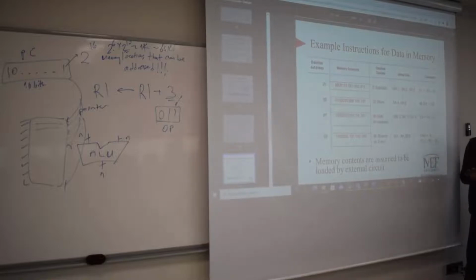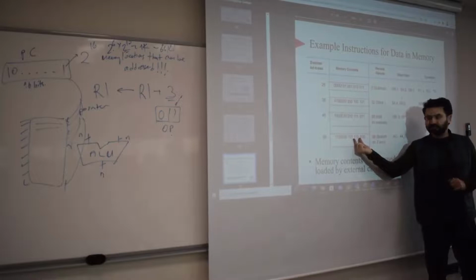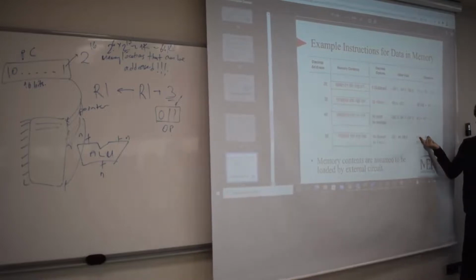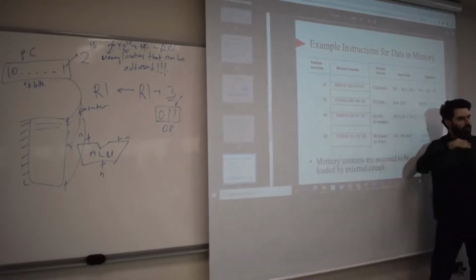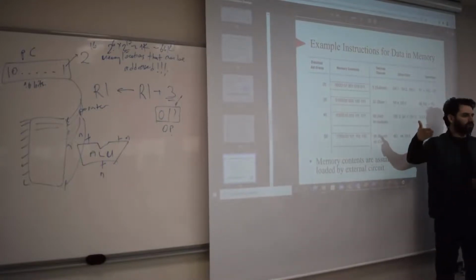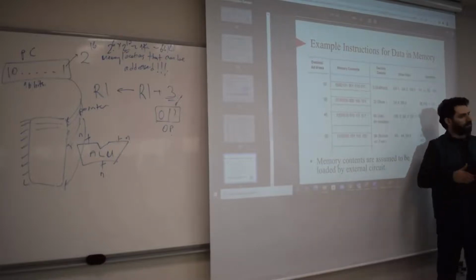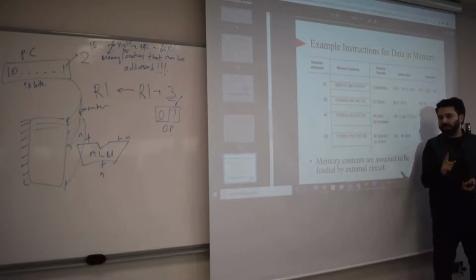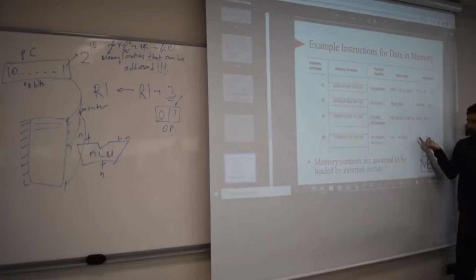But this, of course, happens if you check the register address 110, which corresponds to R6, and check that it is 0. How are you going to do that? Well, you put R6 in one of the buses, okay? And then put a 0 in another register, for example, and put that on the other bus, bus A, bus B. That goes through the ALU, right? If they are equal, there's a condition code for that, right? 0 means equal, actually. So if they are equal, that 0 condition code, or let's just say status bit, is 1, telling you that this is satisfied.